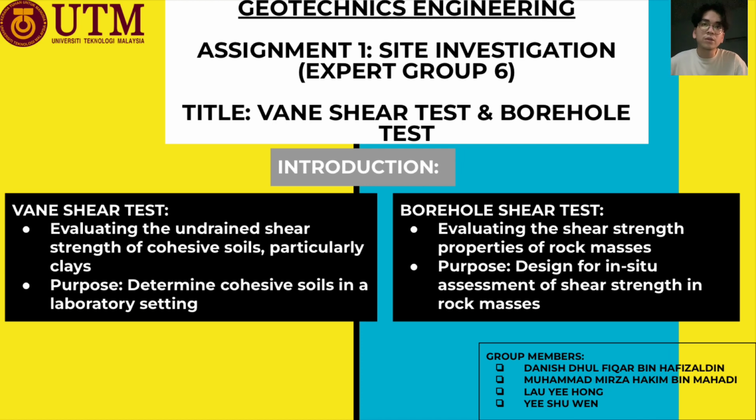So today I'll be sharing about the Vane shear test and also the borehole test. So what is Vane shear test? Vane shear test is a method of evaluating the undrained shear strength of cohesive soils, particularly clays. It serves the purpose of determining cohesive soils in a laboratory setting. The borehole shear test is a method of evaluating the shear strength properties of rock masses. Its purpose is for in situ assessment of shear strength in rock masses.